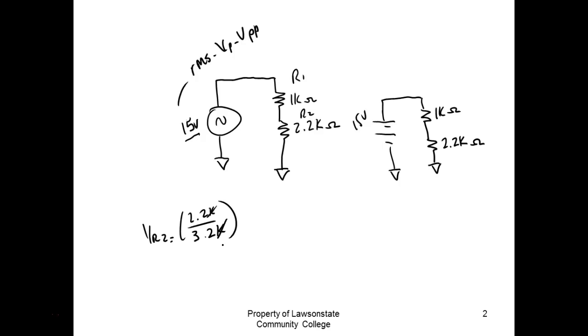And then that's the ratio of the applied voltage that the resistor drops. So you're back in DC and they say, okay, how much would the 2.2K drop if we applied 15 volts? And y'all do all this math. Then they say, okay, what if we raise the voltage to 30 volts? Well, you'd go back and recalculate current and all that other kind of garbage, but you don't, because it will drop 2/3 of the voltage no matter what voltage you put on that thing.